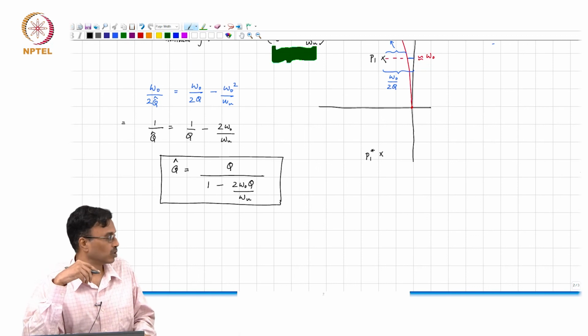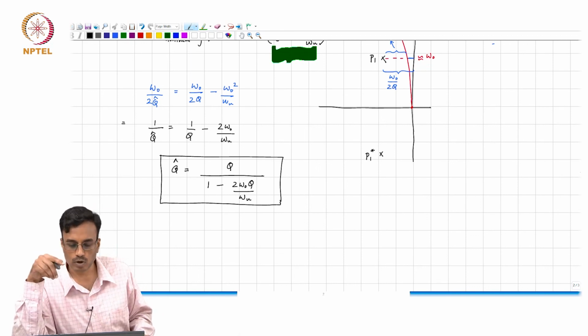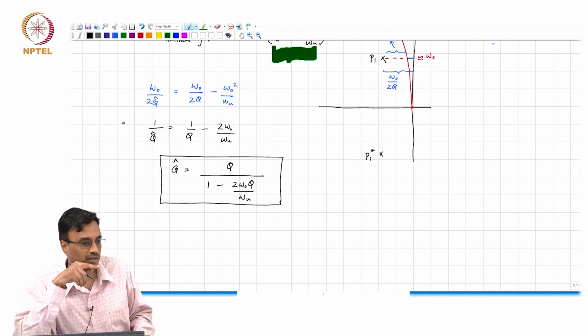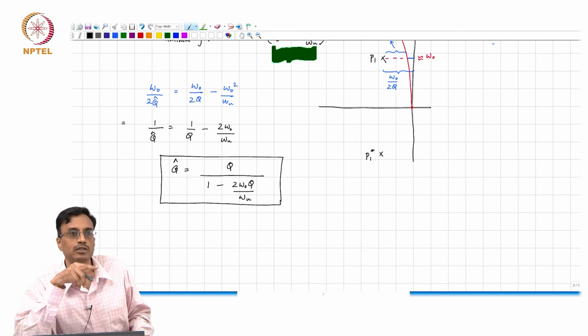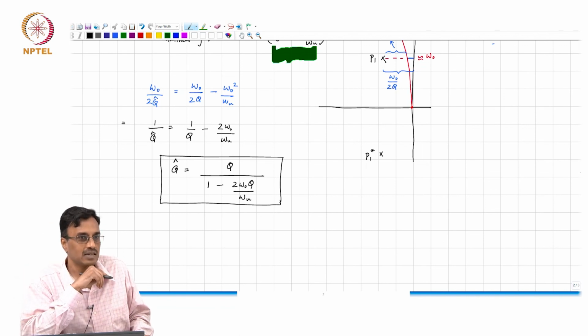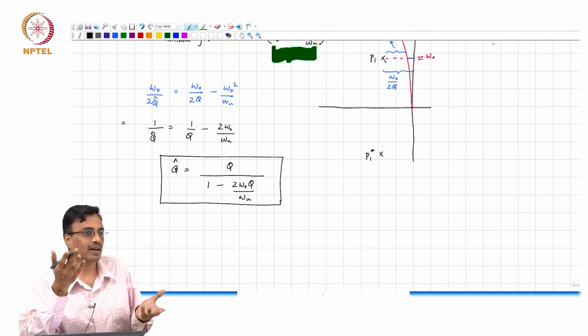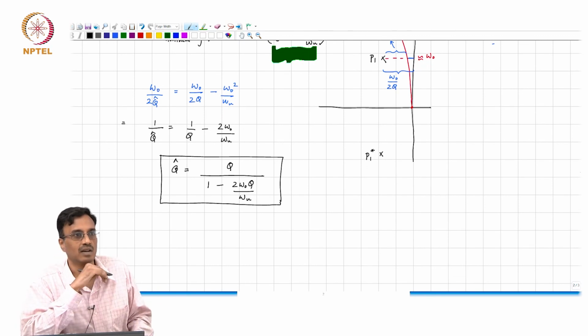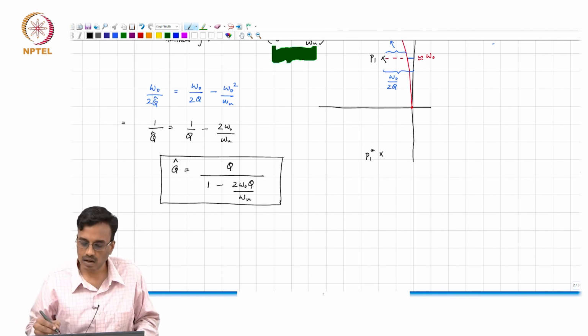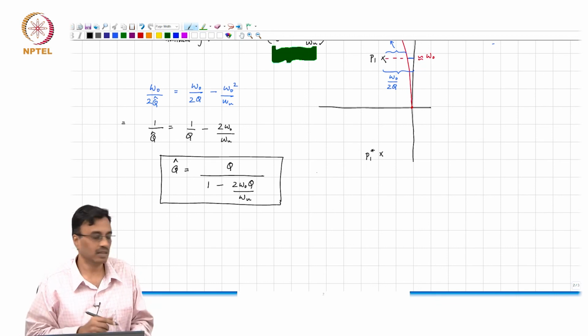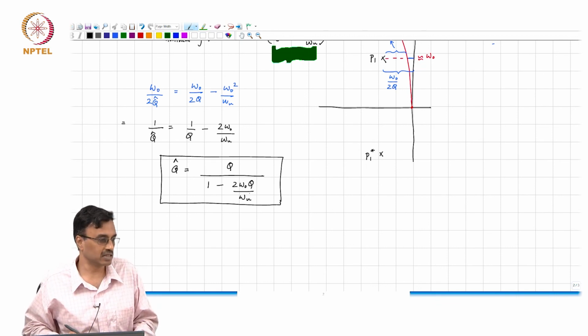Because the moment the op amp has a finite gain bandwidth product, because of the excess delay added by the op amps, the quality factor appears to have been enhanced, indicating in English that the poles are moving closer to the j omega axis, pushing the filter transfer function closer to instability, and the Q is enhanced according to this relationship, right.